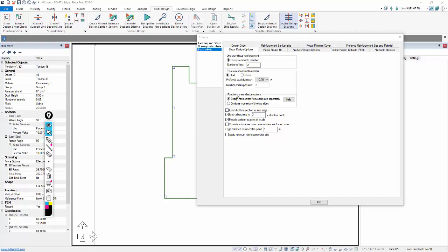There's also this option here, so we're going to leave that at 2, I'll select that. We have the ability to either check the stresses for each moment separately. If we look at the local axis orientation of the column, we have R and we have S. This is 0-degree rotation, and so if we have bending this way and maybe bending this way, we have the vertical shear produced from the axial force, or let's say the load coming into that column vertically, and then we also have our stress due to the bending. That stress can either be combined or it can be checked separately in both directions, and that's what this setting is for here.